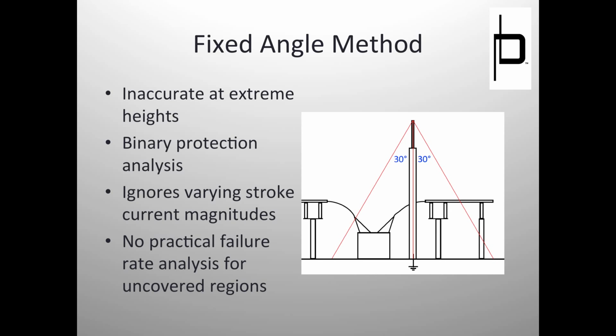I'll give you an example. The best example is something like the Empire State Building. If you imagine it's a grounded structure, it itself is a lightning mast, and it would provide this gigantic 30-degree cone of protection around New York. I know you used to live in New York. I don't know if you lived inside the 30-degree cone of protection of the Empire State Building. But yet, we find that a lot of buildings, maybe such as your building, I don't know, inside its 30-degree cone of protection actually do get struck.